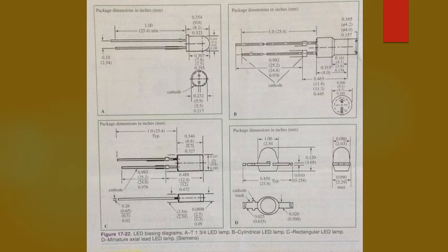Again, diodes can be connected in parallel to improve the current handling ability of the combination over that of only one diode. Care must be used when connecting diodes in a series or parallel arrangement. The electrical characteristics must match exactly, otherwise the current or voltage drop will not be exactly equal across both diodes, even when the diodes have the same part number.